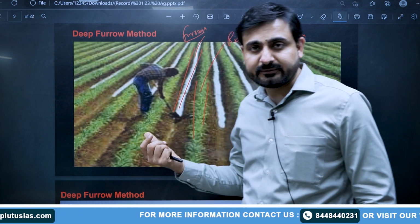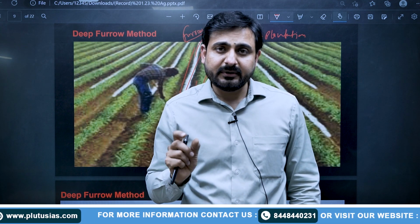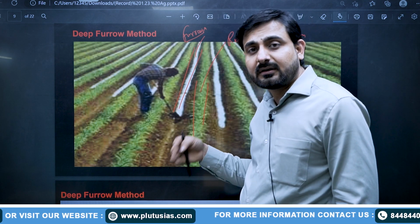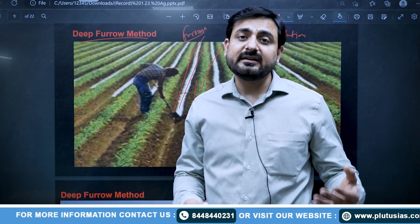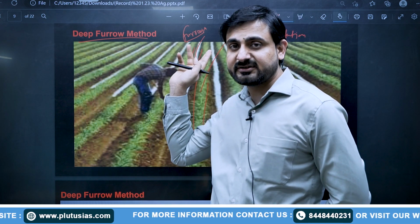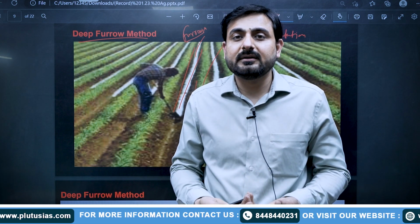Especially in arid and semi-arid regions, regions where there is a low amount of water availability, high temperature, high evaporation, and a little bit of slope over the land, in such regions this deep furrow method can work. Further, in areas where there is heavy rainfall, these ridges are generally transformed into a broad bed.